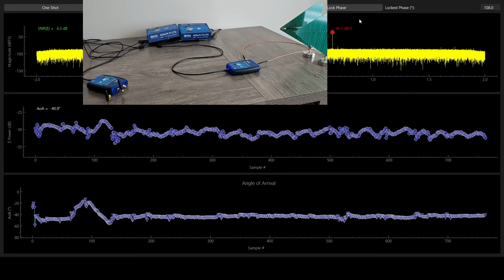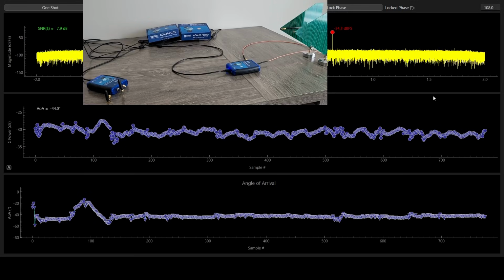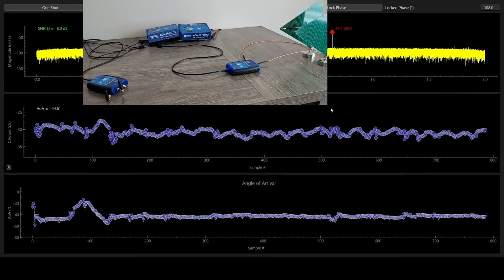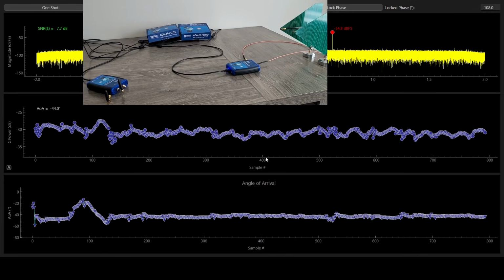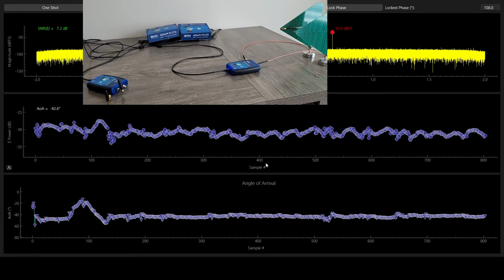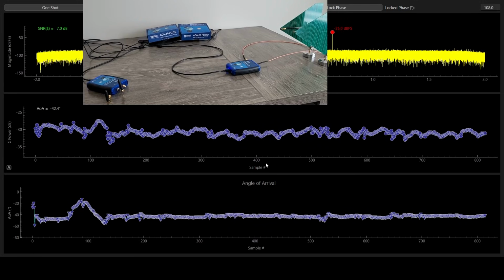And this is the mode that we are right now in. So that TX phase has been swept, and we found that 108 degree is the point that the beam is aligned. But definitely during the span of communication, the beam might get out of alignment.